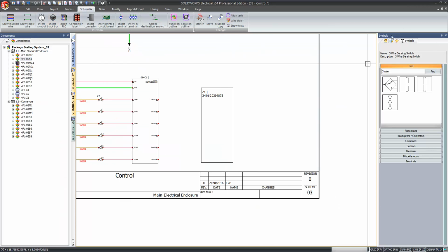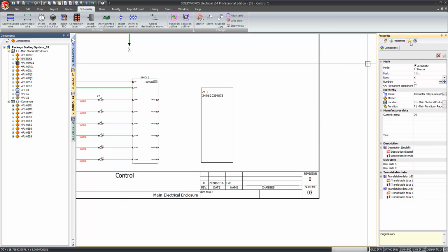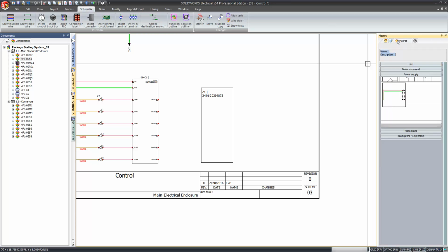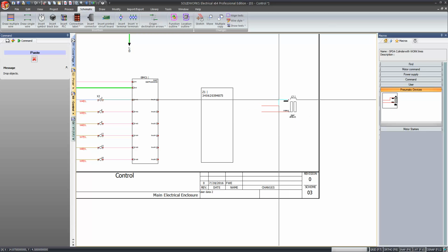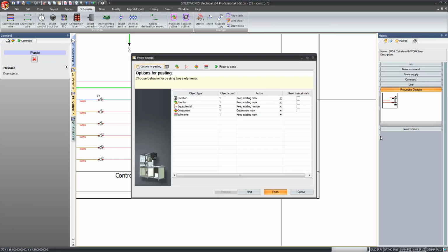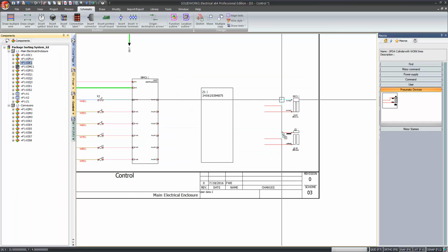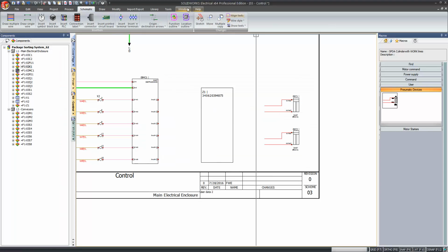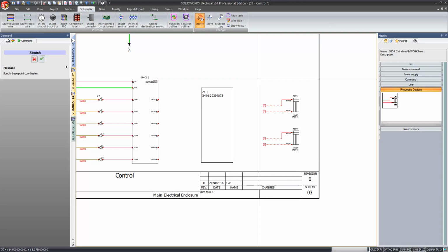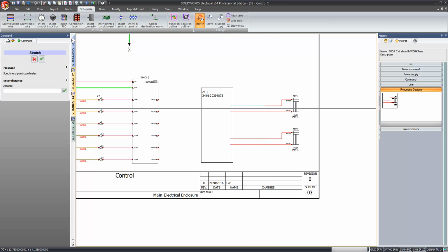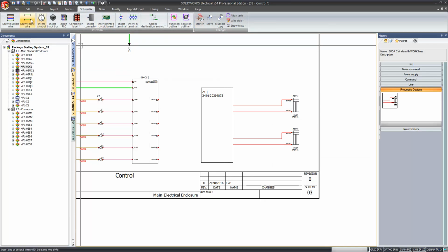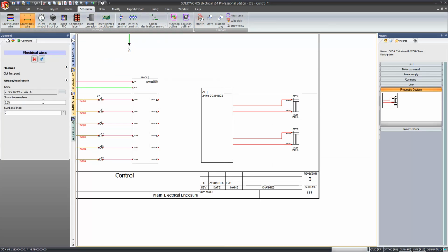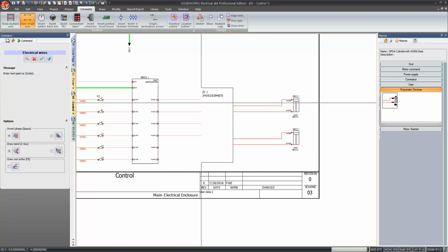And finally, we just want to add the remaining circuits to this device, and that's going to be in my macros palette. There it is. Cylinder, and we'll drag another one in. Finish. Use the stretch command to grab the wires, or hoses in this case. And then we'll create our 4 wires. They're spaced a half inch apart. I'll go to my 4 outputs.